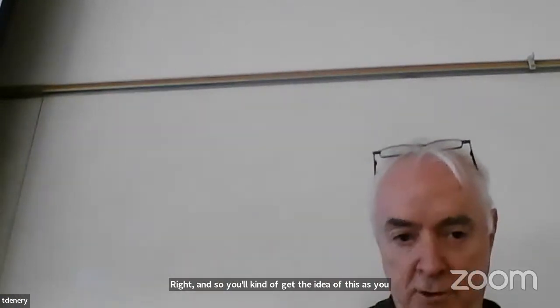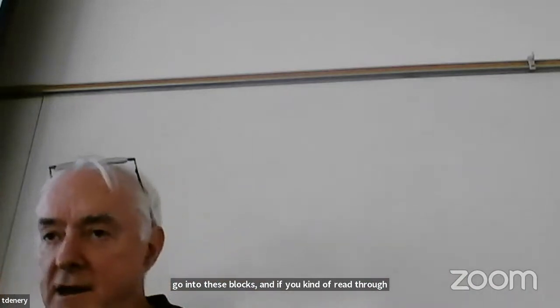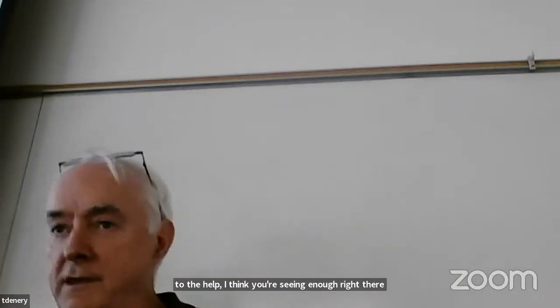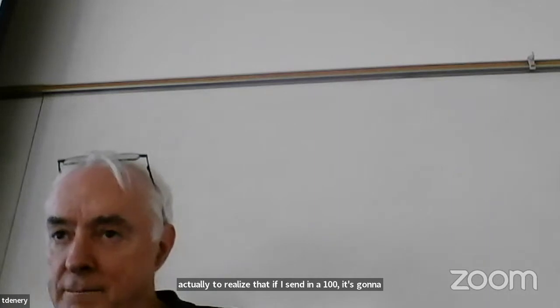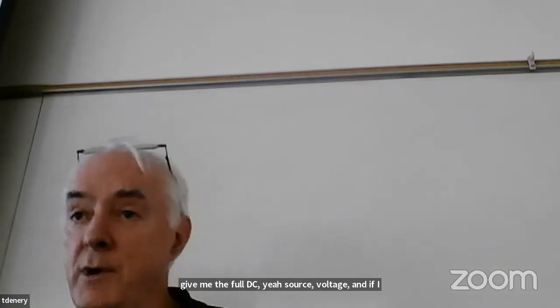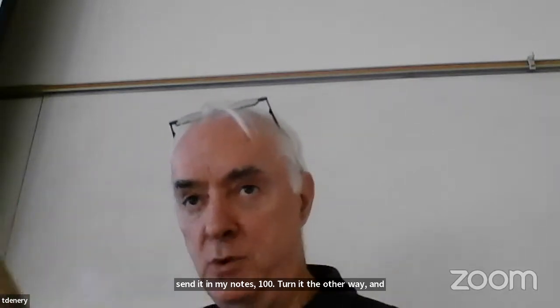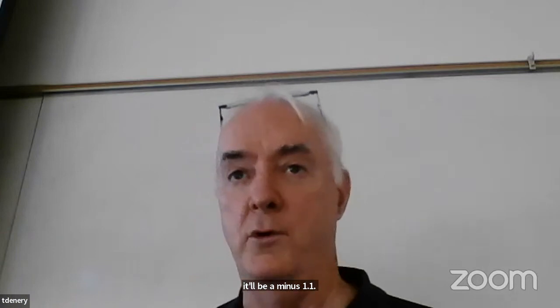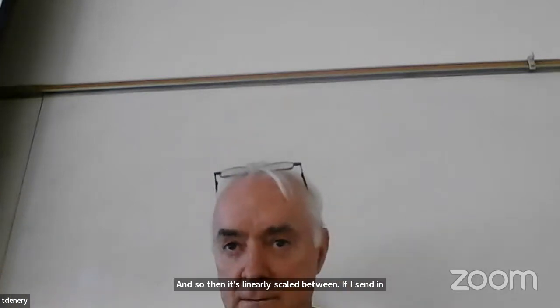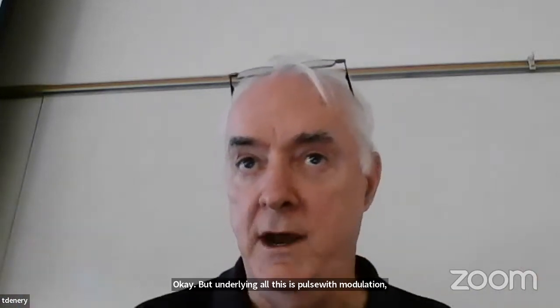If you read through the help, I think you're seeing enough right there to realize that if I send in 100, it's going to give me the full DC source voltage. If I send in a minus 100, it turns the other way, and it'll be a minus 11.1. It's linearly scaled between. If I send in a 0, it puts in 0 voltage. Does that basically make sense? Yeah. Okay. Underlying all this is pulse width modulation, implemented through the Arduino IDE.